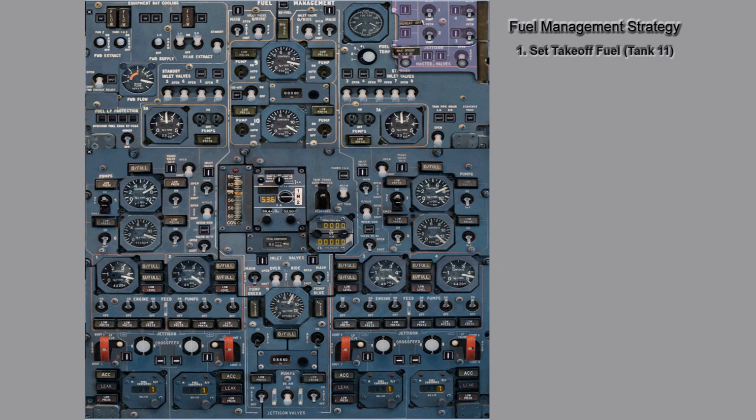So that's step one. The next step is we're going to have to move fuel back once we hit a speed of Mach 0.7, which is actually great news, because from the time you set your takeoff CG, or takeoff fuel in tank 11, to the time you're well on your way, you've got your automatics going, your INS is all controlling the plane, you're climbing probably through well over 10,000 feet, I'm guessing.